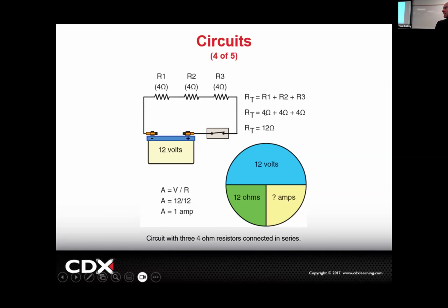Now, that's how this circuit's designed. A lot of times in the field, it's like you had a 4-ohm bulb, and then you had another unwanted resistance that's like some random number. It's so rare to see it so equal and beautiful. You'd be like, hey, I've got a 4-ohm bulb, but then I've got like 197 ohms of corrosion resistance or something, some weird number. But yeah, that's exactly right.